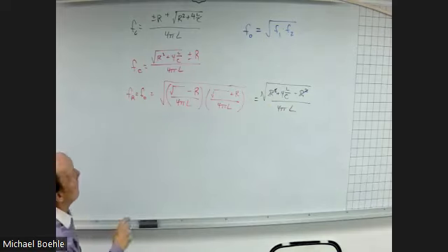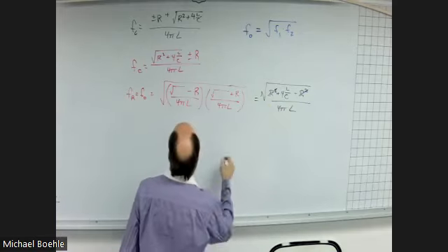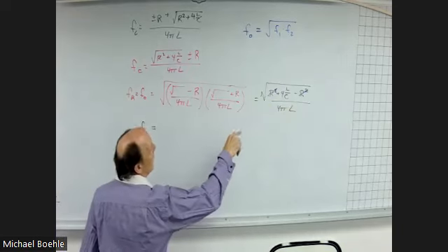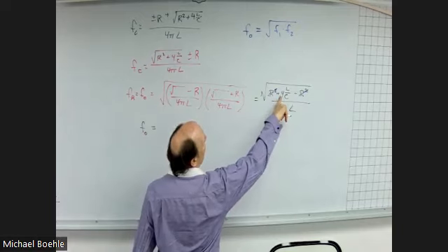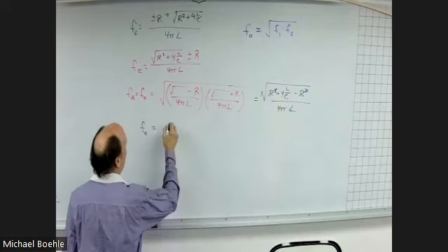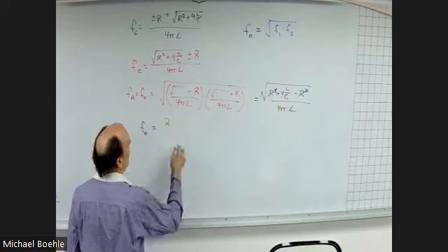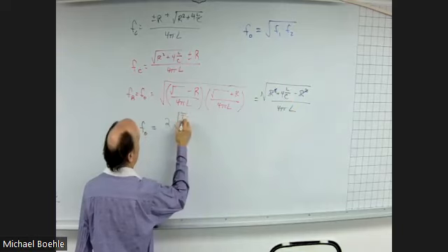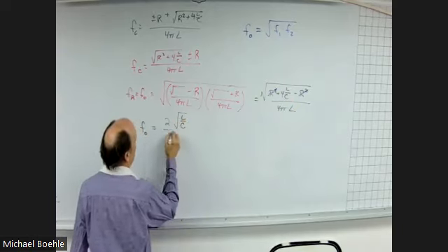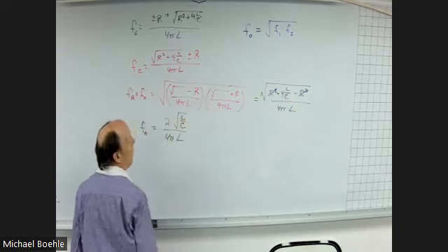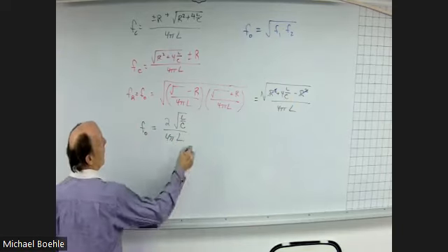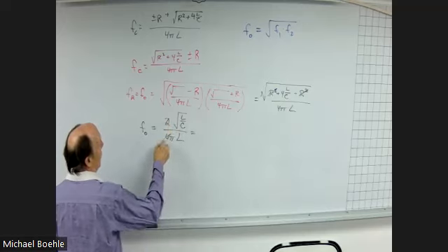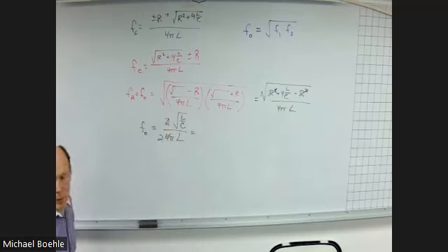All right. So what does that leave? Well, that means that center frequency will be, so the square root of 4 is 2, and then I have the square root of L over C divided by 4 pi L. So divide top and bottom by 2. 2 goes away, 4 becomes 2.